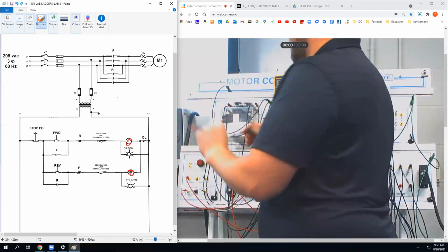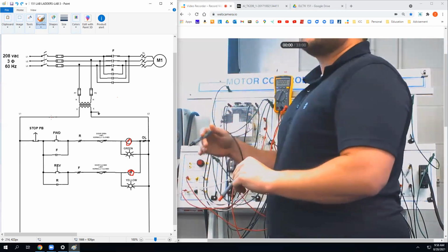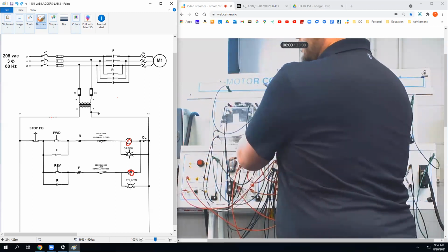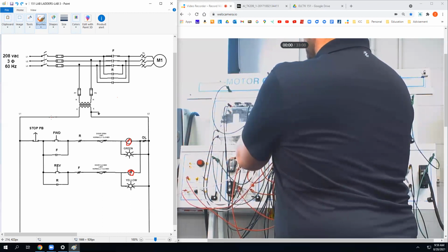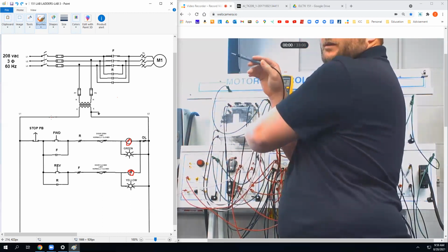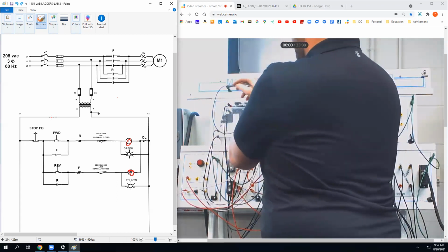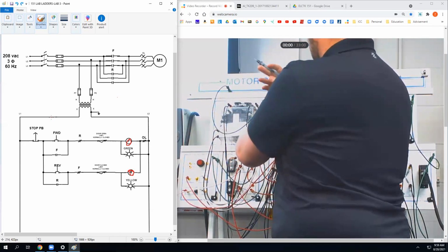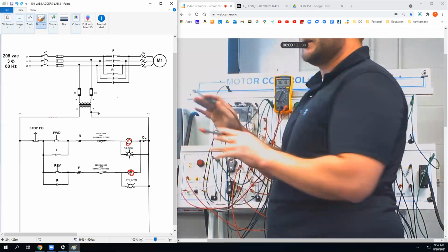I've seen that a lot, but a good practice would be to go to your neutral first, because it's reference to ground, and then there. If I touch this, I'm okay. I don't want to, because I never want to just be careless like that. But this is reference to ground. I'm grounded, and I'm not a good current path. So if I touch that, I would be okay. But I just want to put that out there in case you didn't know.